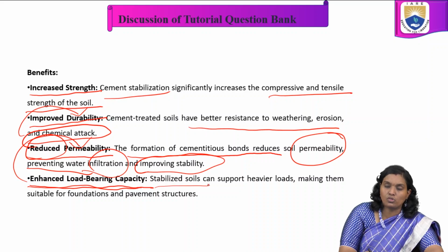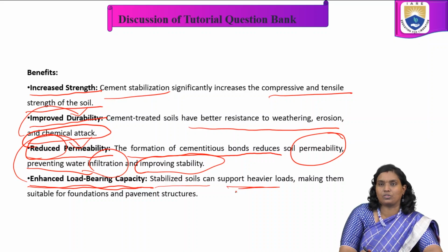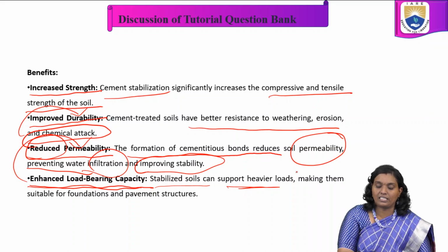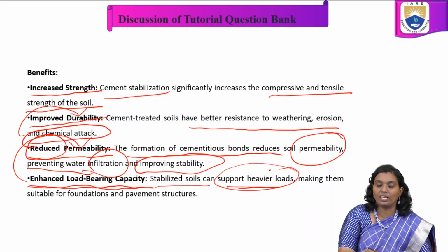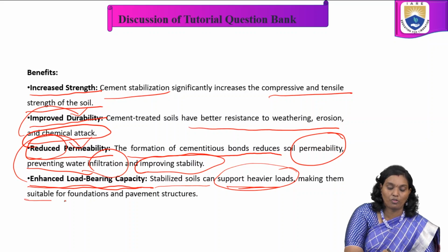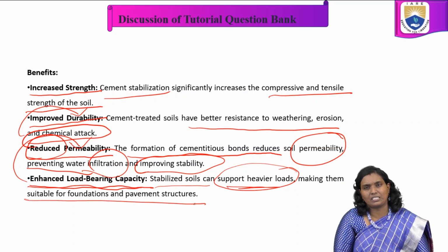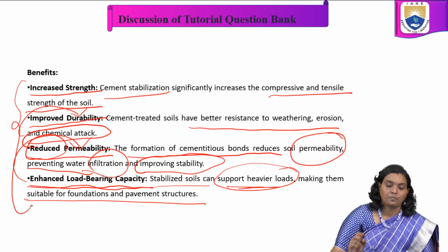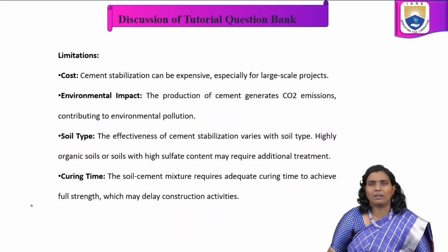So it leads to reduced permeability and enhanced load bearing capacity. Stabilized soils can support heavier loads. Because of cement stabilization, the soil is strengthened to support heavier loads, making it suitable for foundations and pavement structures also. These are the benefits which we observe in cement stabilization.